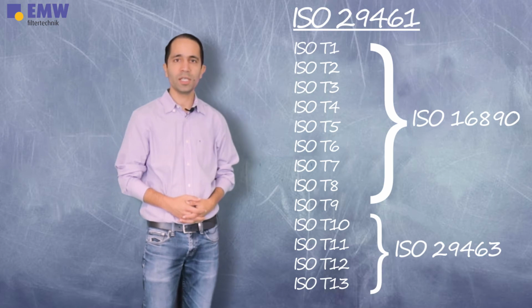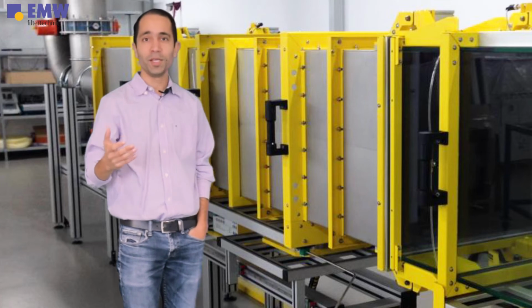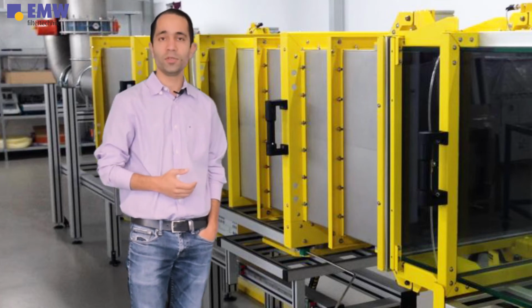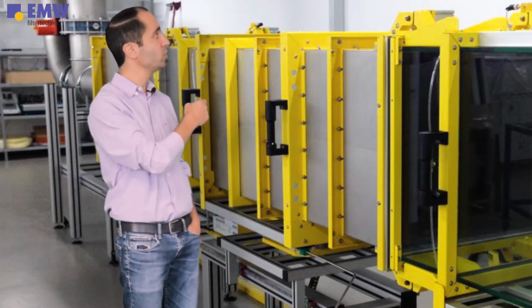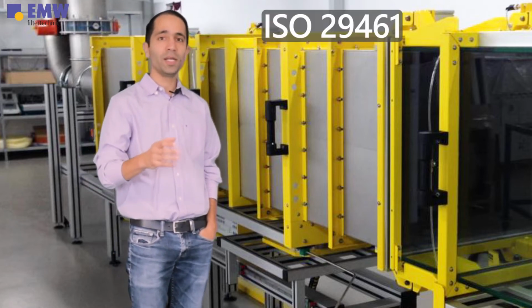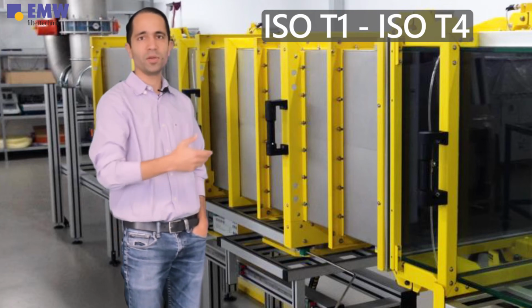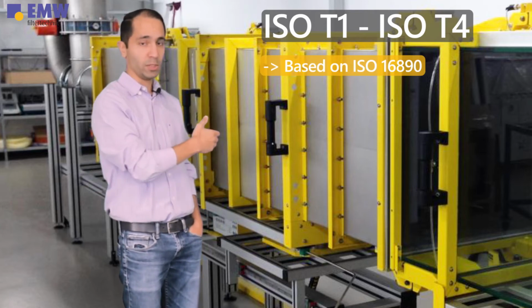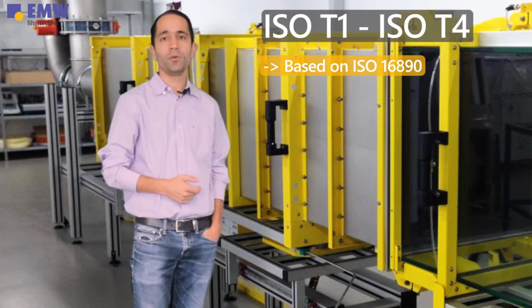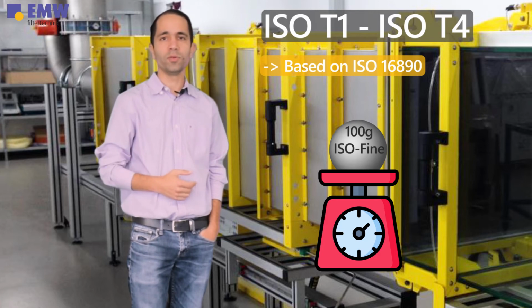So this is a short introduction, but I would say it's worth spending a little bit of time on the test rig, where we can see how the test procedure runs. So now we have reached the test lab, and in such a test rig, which you can see over there, we check the performance of filters like pocket filters or compact filters. With regards to the test standard ISO 29461, I told you already that the filter classes T1 to T4 get tested based on the existing test standard ISO 16890. That means during the test procedure we measure the initial arrestance of the filters until a dust load of 100 gram with the test dust ISO fine.